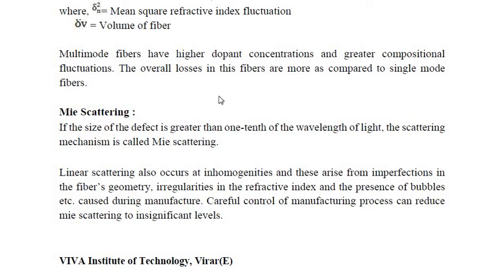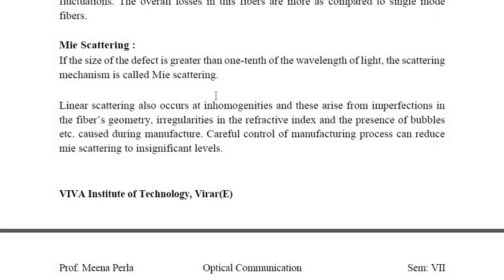Mie scattering loss. If the size of the defect is greater than 1/10 of the wavelength of light, the scattering mechanism is called Mie scattering.